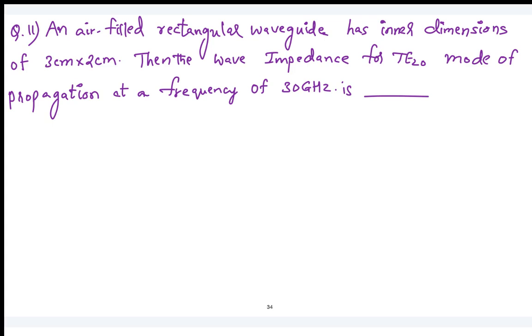When you are talking about a transverse electromagnetic wave, I told you, when it is moving in free space, the impedance will be 120 pi. Isn't it? Now, what will happen when you want to define impedance for TE? I told you the transverse electric wave, recollect exactly, it is an example of the S polarized wave, or a perpendicular polarized wave where you will have the electric field in y direction and magnetic field on the XZ plane.